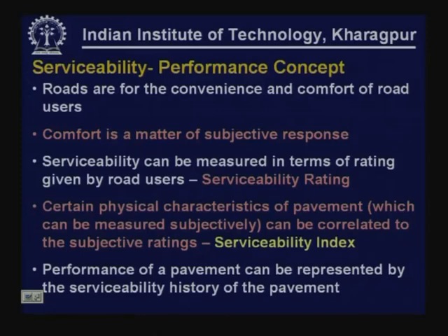What is the serviceability performance concept? We know that roads are for the convenience and comfort of the road users. Comfort is a matter of subjective assessment. What is comfortable to me may not be comfortable to you, but when you have the collective assessment of a given road by a number of panelists or users, we will get some idea about how a particular road is rated by different people and how the rating of a particular road is different from the rating given by the same panel to another road having different condition.